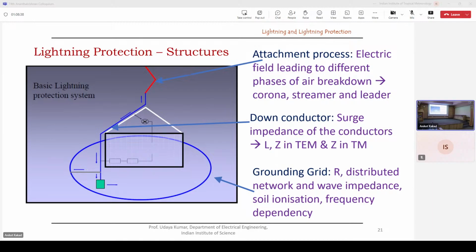One thing we need to worry about is electric field intensification, which is responsible for the local discharge of air called corona, streamer, and leader. I will take the subsequent slide to define this terminology. In other words, this is a microscopic phenomenon. Remember, your gap and structure are in meters, hundreds of meters. This is in micrometers, this is in millimeter scale, and this goes in meter scale.